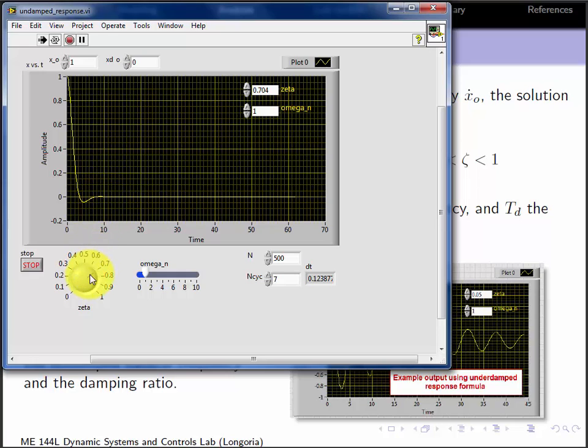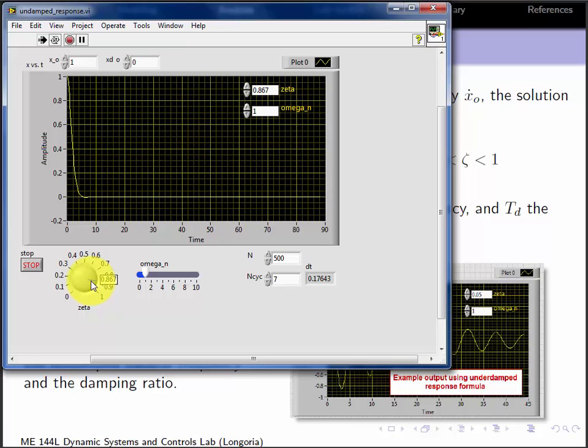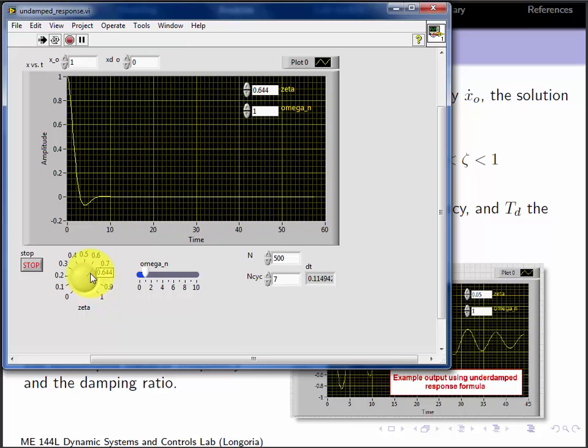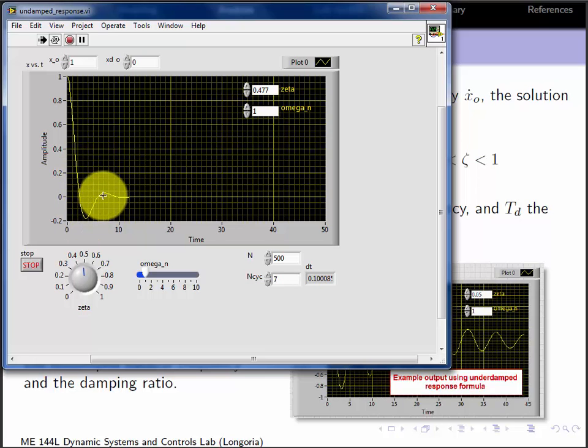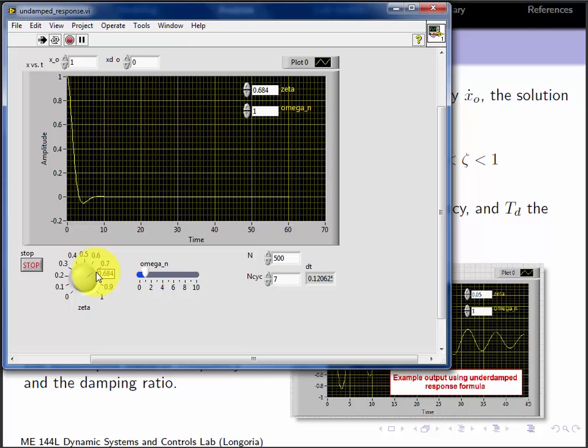And also it's the fastest kind of time to get to that value. Once you go above that, it's a little slower. You get less overshoot, and finally you're almost overdamped. And if it's less than 0.707, you can get there faster, but then you've got oscillation. So that's why 0.707 is kind of a special value.